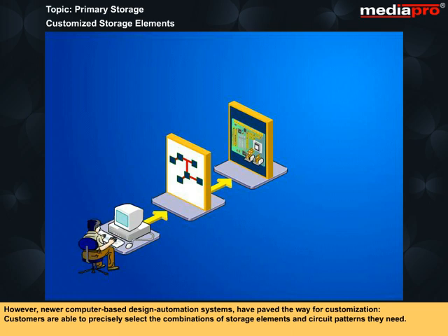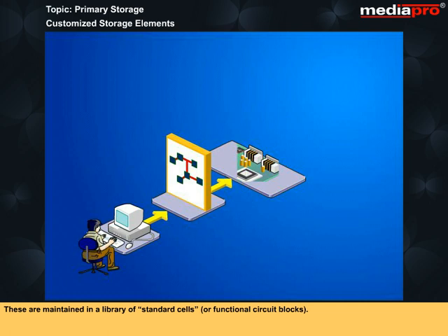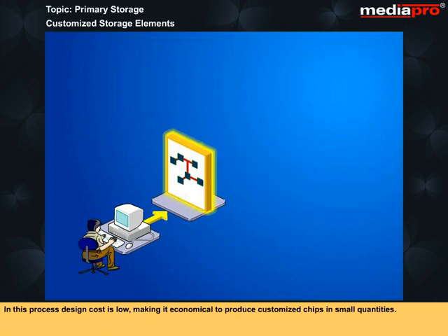Customers are able to precisely select the combinations of storage elements and circuit patterns they need. These are maintained in a library of standard cells or functional circuit blocks. In this process, design cost is low, making it economical to produce customized chips in small quantities.